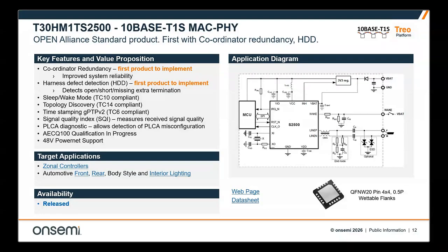So additional features included the TC10 compliant sleep and wake, the TC14 topology discovery, gPTP version 2 timestamping, a signal quality index that measures received signal quality, and PLCA diagnostic for detecting misconfiguration. So the device already supports 48-volt power nets and is currently in AEC-Q100 qualification.